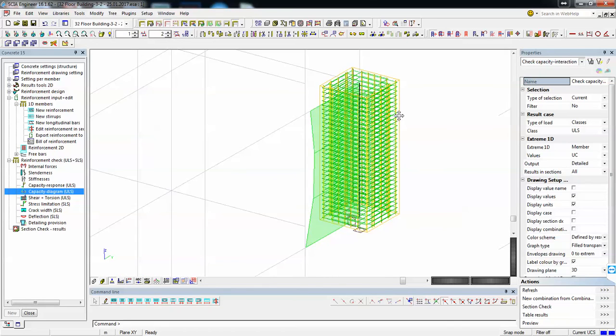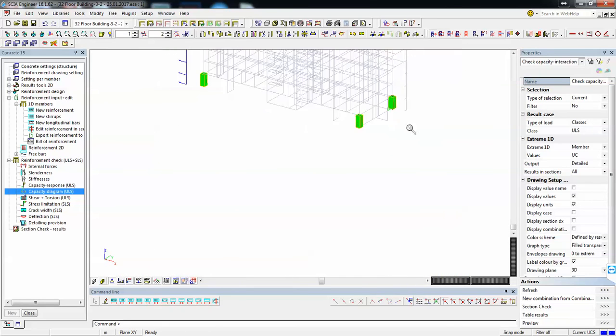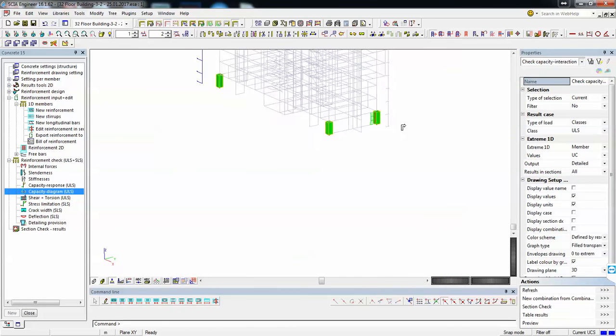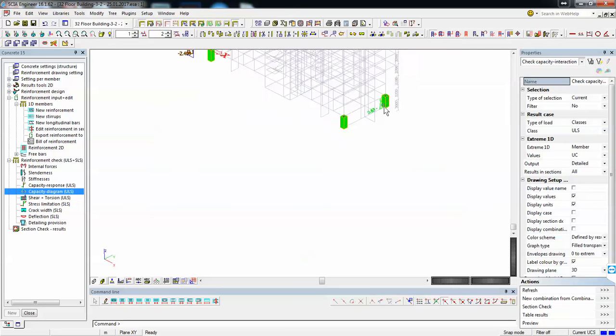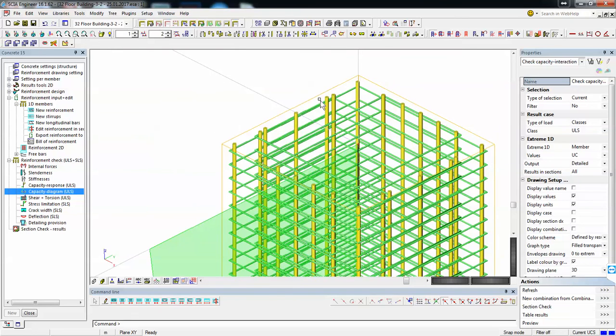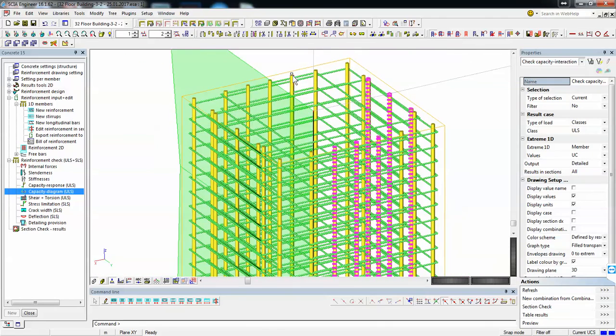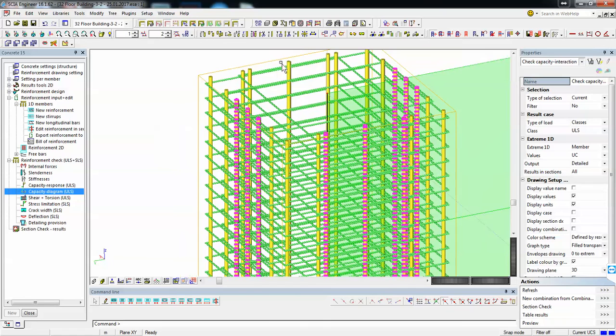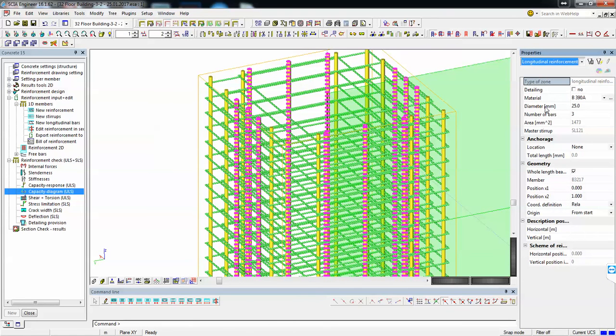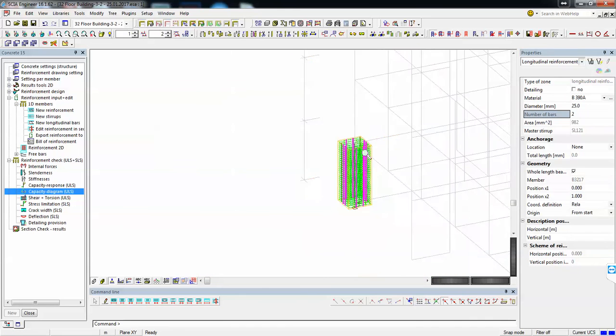You see here we have too many bars, but you decide whether you want symmetry and reinforce them the same, or if you want more optimized, you can start reducing the number of bars, and you might have a better, more economic solution. You just add elements upwards and try to find a safe and economical solution.